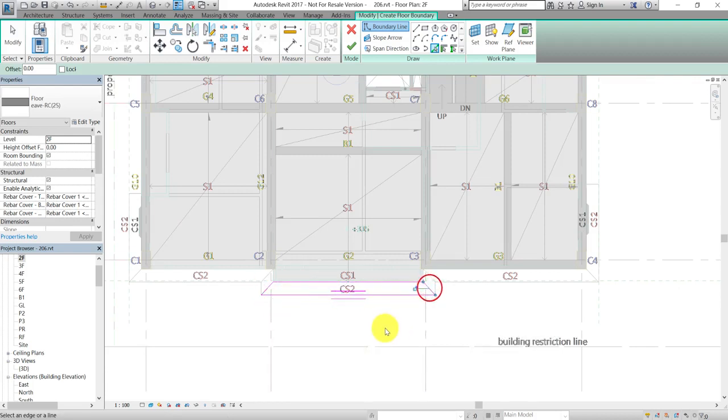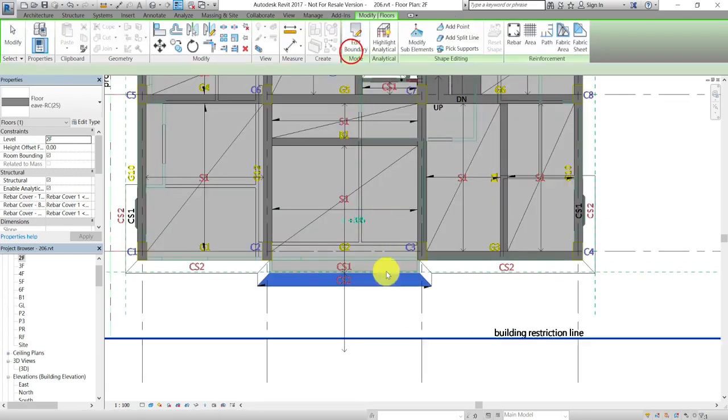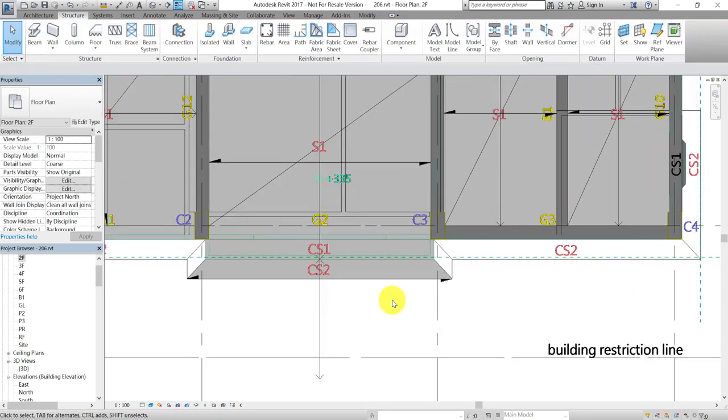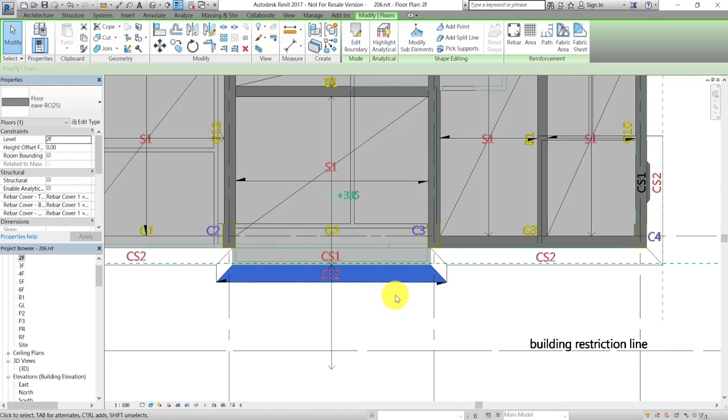At the intersection of two eaves, we may make a 45-degree angle for both of them so that they can match each other in shape. Click the green check icon to finish creating this eave. Also, we need to create a slope on its surface. Select the eave first.